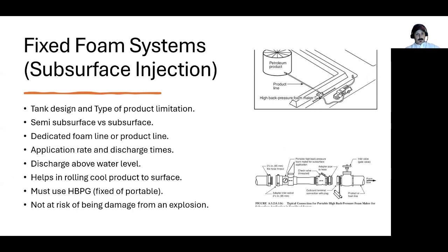As we said, we need to discharge the foam above the water level, otherwise the foam will be destroyed. And also this system, when it's a fully subsurface, not the semi-fixed semi-subsurface system, will help in rolling a cool product to the surface of the burning liquid.